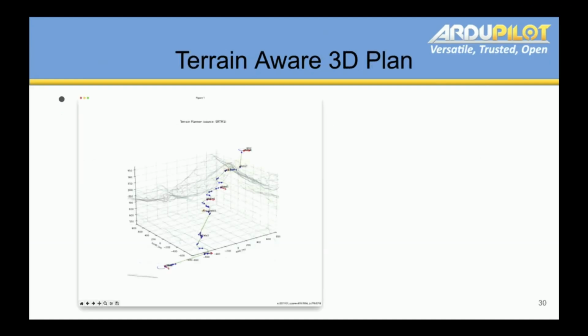So here's an example where we do have terrain, and the general structure of these things is straight lines with curves, and there's a constant climb rate along either the curves or the straight lines. If you can't hit a state going from one point to another, the model will spiral upwards. So you've got curves, or you're spiraling, or you're going in straight lines. And any path you'll see created by a Dubins style planner will have that structure.